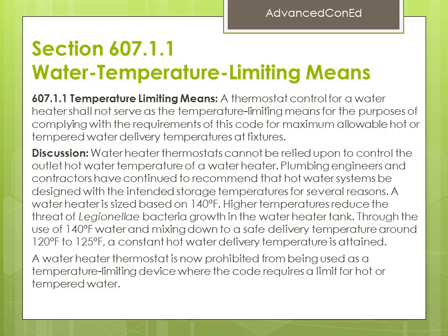Discussion. Water heater thermostats cannot be relied upon to control the outlet hot water temperature of a water heater. Plumbing engineers and contractors have continued to recommend that hot water systems be designed with the intended storage temperatures for several reasons. A water heater is sized based on 140 degrees F. Higher temperatures reduce the threat of Legionella bacteria growth in the water heater tank.